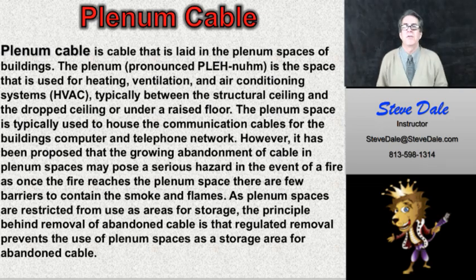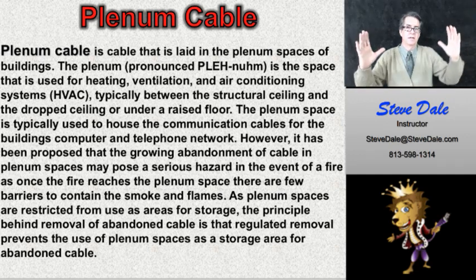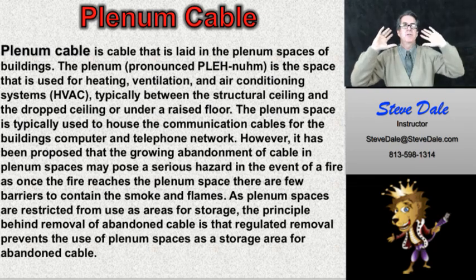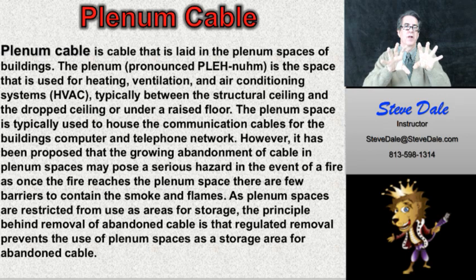In commercial buildings, you have these areas that are used for the return of air that people breathe, okay? And those are referred to as plenum spaces. Now, it could be a duct, an actual metal duct of some sort that has a return attached to it, and inside there would be considered plenum space. But more so than that, and what we're really concerned about, is keeping our conductors and wires out of plenum spaces unless they are plenum rated for fire retardancy and low smoke emission, okay?